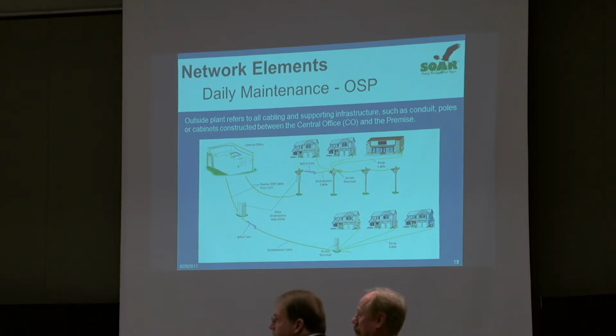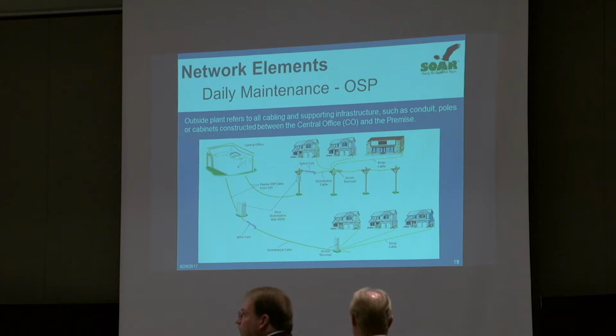Typically on the routes that we have, it's a middle mile network. We're running up and down those roads at least once a month, just making sure. The other thing, I mentioned that I look at poles. If you're going up and down the highway and you see a pole sticking up with a little orange top on it, that means there's fiber optic cable buried underneath that location. And those are typically the locations where we're going to go in and put tone on and then plant in case somebody's going up and down that roadway. So that's the portion on ours.